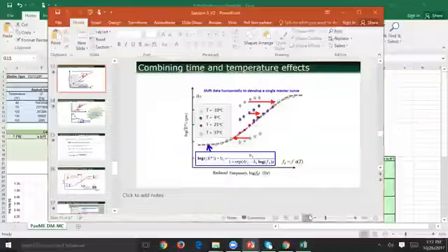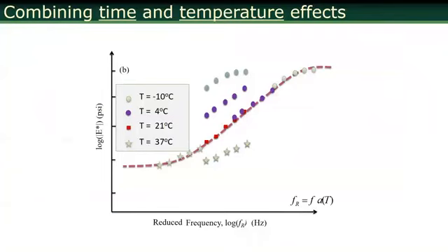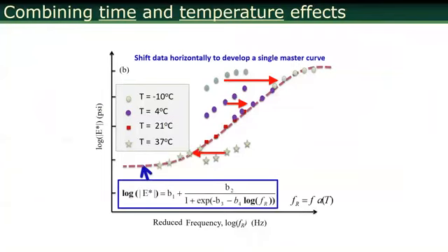If you look at this slide, when we were talking about development of the dynamic modulus master curve, this equation and that equation are identical, except instead of the logarithm of time, we used the logarithm of frequency. That's the only difference between the two equations. That's why the curve looks this way here, and in Pavement ME it looks the other way.